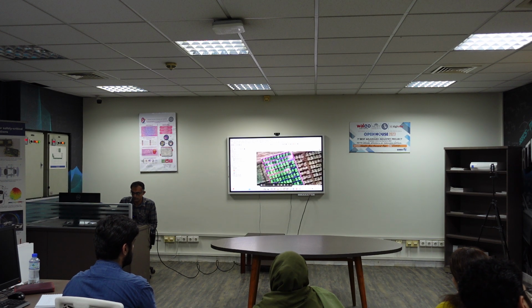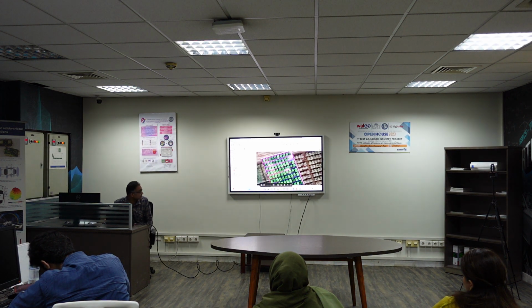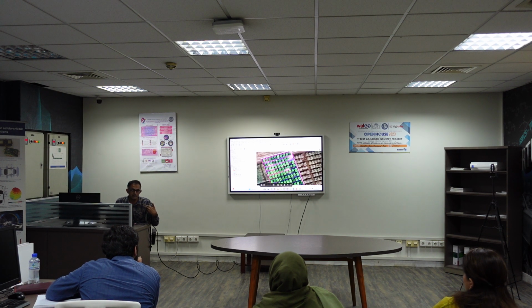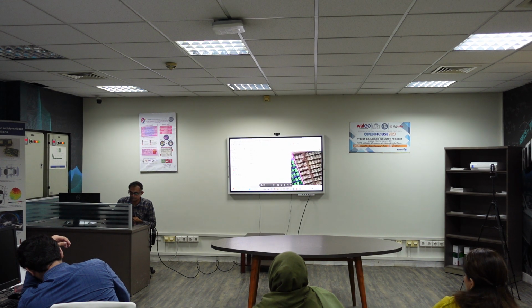For that, we have already covered that we have raster data and vector data. This is raster data. Raster data is not as efficient for objectively quantifying something, so you are required to convert this data into vector data. One thing you can do is draw polygons over each of these plots, and then tell the software to give the average value of that NDVI. That's what we are going to do. One manual way of doing this is going into the layers, create layer, new shapefile, because vector data is also known as a shapefile. So let's see.